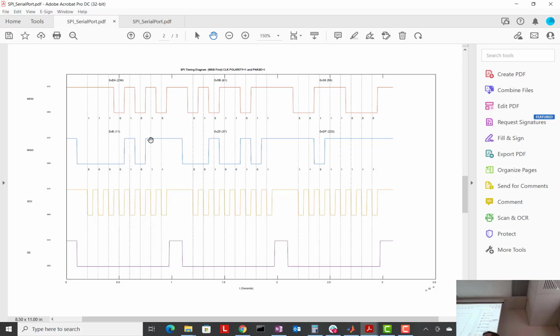So that is one way, when you're looking at an oscilloscope and you don't have my nice dotted lines right there, to indicate to yourself what edge it is transitioning on, what edge it is reading the data, right? Does that make some sense?